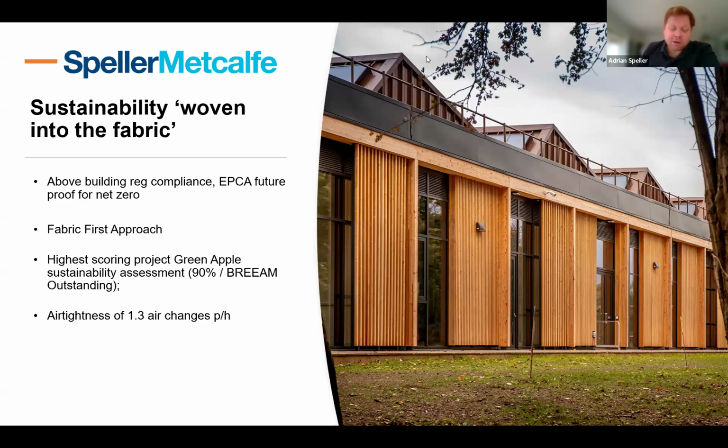We were under something called a Green Apple assessment, so it's bespoke to Herefordshire Council, but broadly aligns to BREEAM, and achieved a 90% score under that holistic sustainability assessment, and a final air tightness result of 1.3 air changes per hour using a passive house methodology, not a UK building regs methodology.